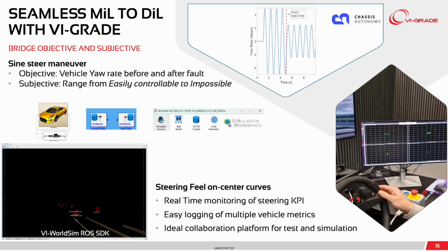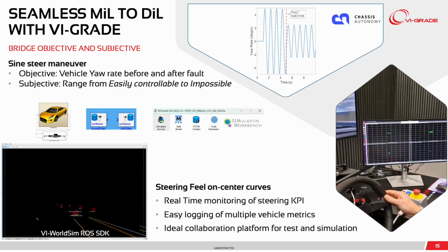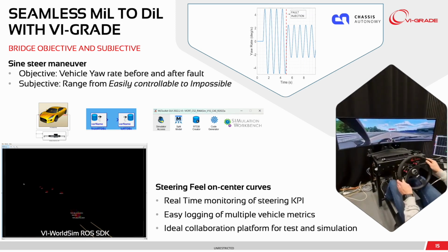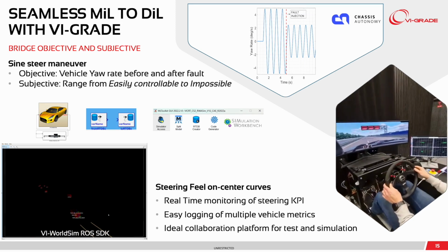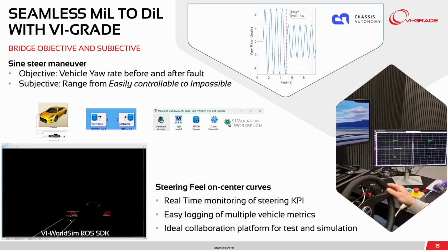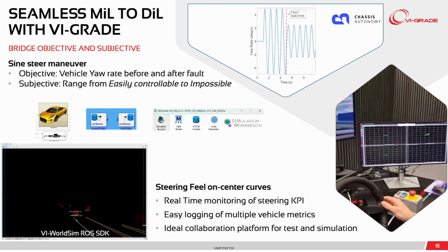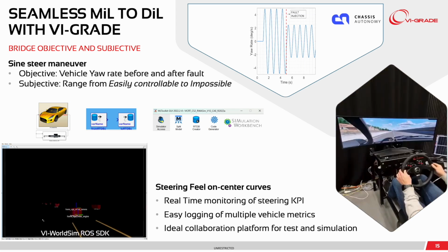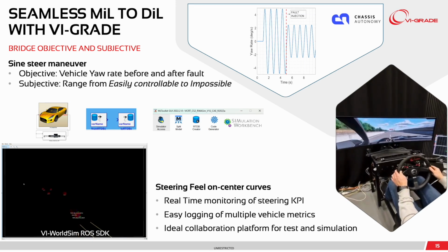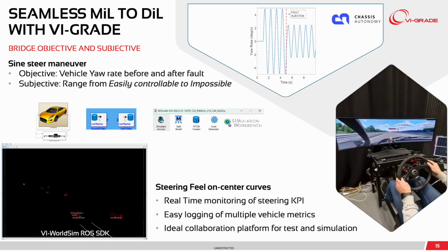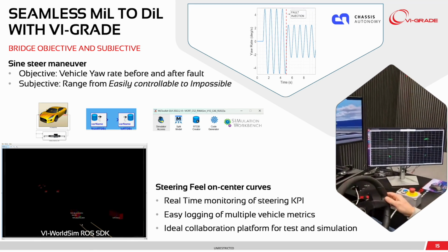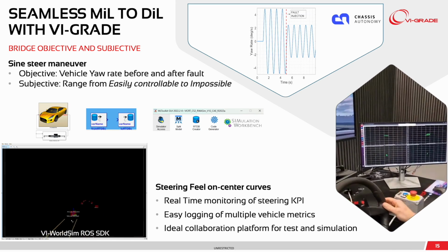If you are working towards an autonomous driving customer, maybe a robotaxi customer, what you can do is send out your vehicle model on something called a data drive or a synthetic data exploration. What these robotaxi players do is they operate in a specific environment called ODD, operational design domain. If you can get hold of this ODD, you can optimize your control algorithms, and you can optimize your actuator motions for that specific ODD.